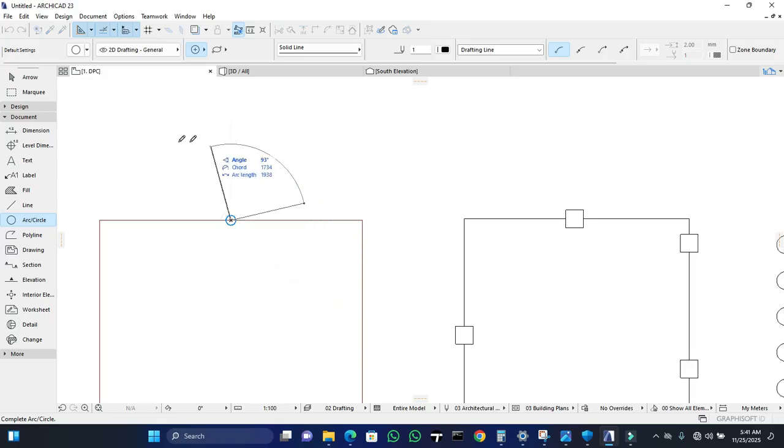Now I'll have to specify how far I need the circle to go. I'm just playing around. If I want it to be a full circle, I can turn it around and come back there. Click OK. So let's do it again. Click on circle with this option selected, hover around the center, click on it, specify my radius 1200, hit enter. Then I draw my circle.